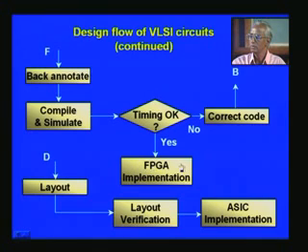And so this basically is a software path, we can say, and parallel to this, right from the inception when you have frozen the specification, you should also start the hardware work. For example, you should know the FPGA, and with a few exceptions you can change the IO pins, as we have seen before, because through user constraints you can specify the IO pins.